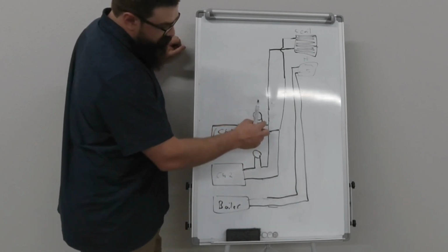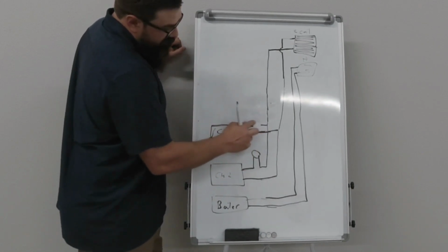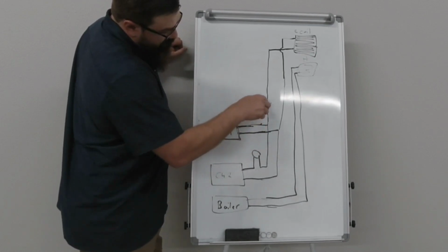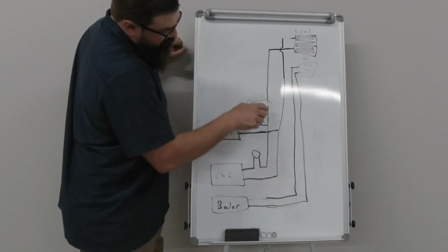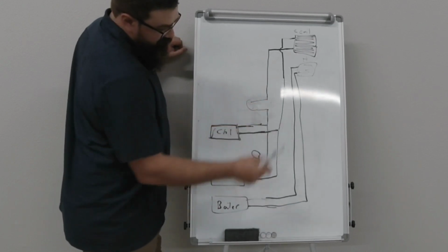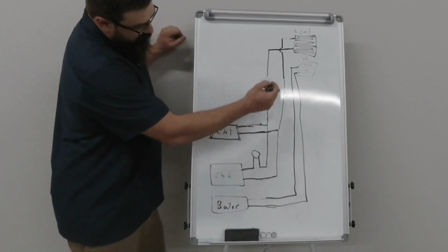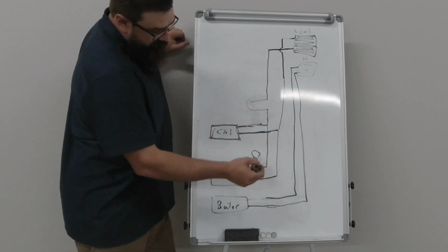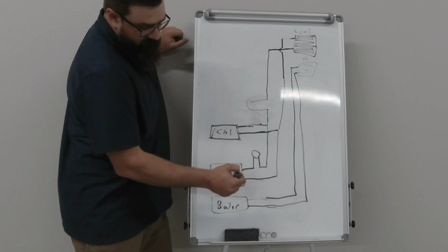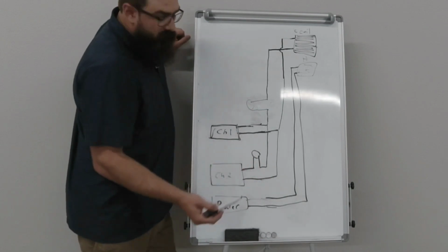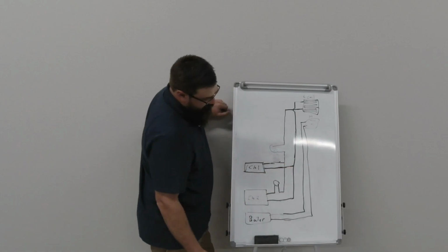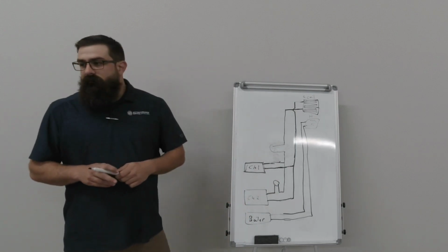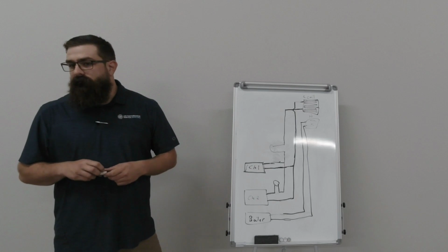Whereas in a common, that would be your pump over here feeding both chillers together. So common comes through the pumps, and can push to both chillers. Dedicated is the pump can only push through its chiller.